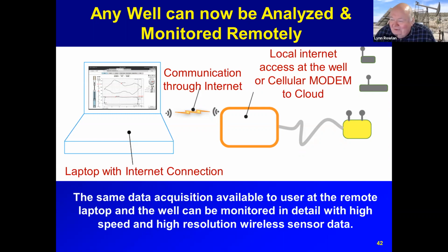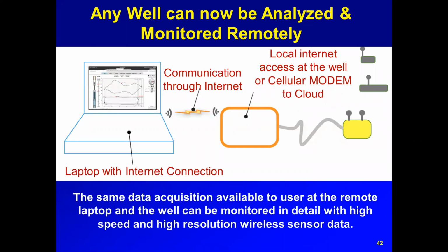So when you look at that, you say, oh, I got a fluid level that looks like a tornado or funnel. Then you have to use the software to look near the surface at the beginning of the shot, identify the kick, and you can determine the thousandths of a second to liquid level, and every thousandth of a second is like 6 inches. So yes, you just have to work a little bit harder at it because you have to not use too much pressure, and then you have to identify the kick.